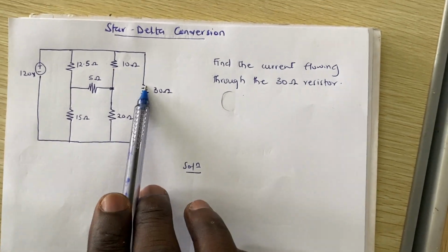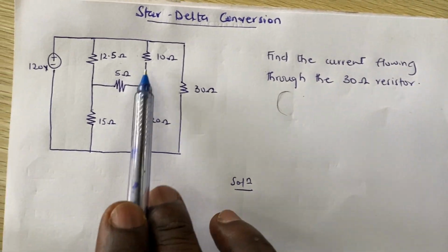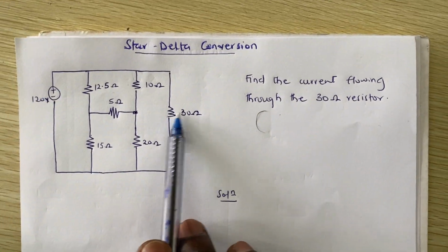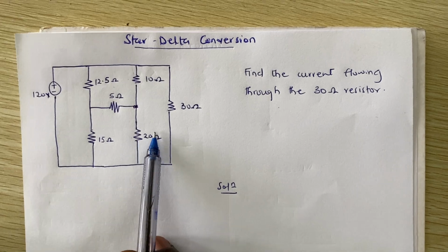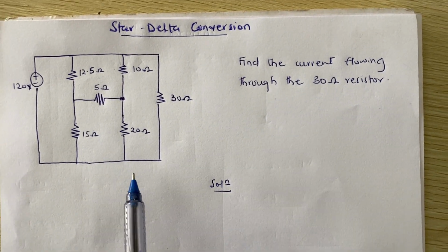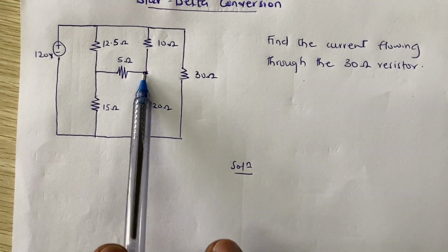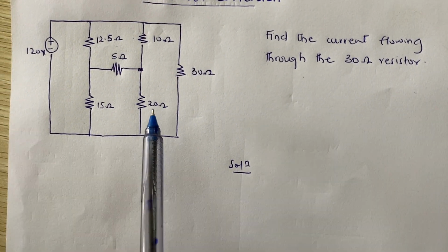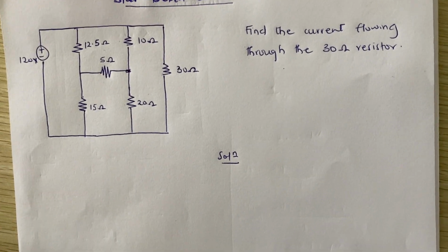And when you take these three too, this tip is connected to this, and this tip is also connected to this here, right? So it means that this is also delta connected, right? So now we can choose to convert any way possible that we want, either change this to star, this to star, this to star, or the middle one to delta, right? So let's start by changing this middle one to delta connection and see how our circuit is going to look like, right?